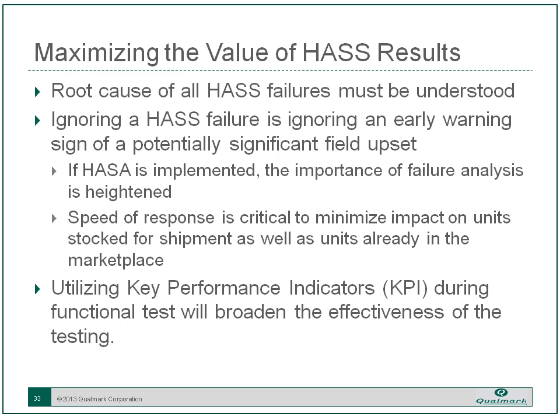In HASS, it can be particularly important that you get down to that root cause analysis on all these failures. As I say, a HASS failure is an early warning sign of a potentially significant field upset. You're catching the fringes of distributions when you push out in HASS. And if something has shifted at a vendor's facility, you can spot it in HASS. If you say, well, that's kind of a weird failure, let's see if it pops up again, and then make a decision on it, that can be an extremely dangerous, expensive line of thought.